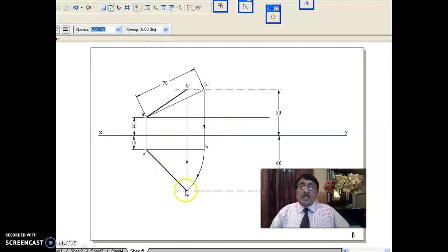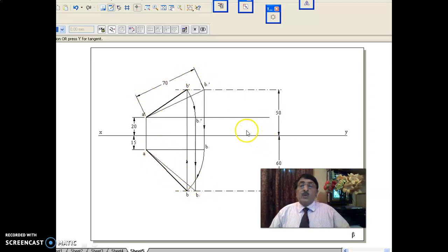Now since top view is here, top view I have already rotated, I got the true length, true inclinations and all that, which are already done by no procedure. But now to get the true length here, one procedure is take same 70, cut it here. Otherwise, rotate front view parallel to XY line and hit against the locus, and join this, you are getting the true length. This true length will be same as this true length only. In that way, true length and true inclinations, everything you got.